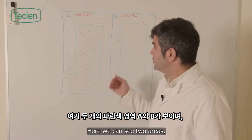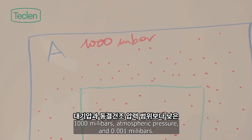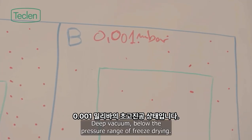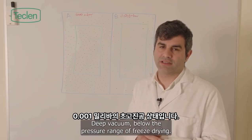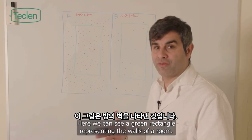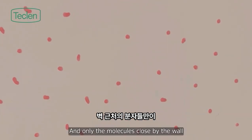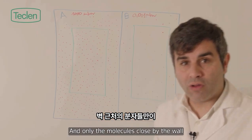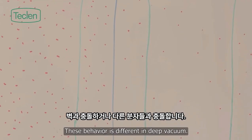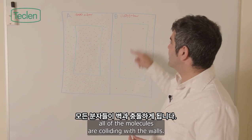Here we can see two areas drawn in blue, A and B, with two different pressures: 1000 millibar, atmospheric pressure, and 0.001 millibar, deep vacuum below the pressure range of freeze drying. Here we can see a green rectangle representing the walls of a room. So the molecules at the center at atmospheric pressure are mainly colliding between them, and only the molecules close to the wall are colliding with the wall and with molecules. This behavior is different in deep vacuum. Because of the low density of the molecules, all of the molecules are colliding with the walls.